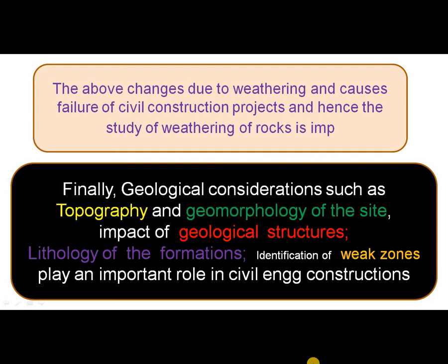And finally, geological considerations such as topography of the area, geomorphology of the site, impact of geological structures such as folds, faults, joints, etc., lithology of the formations in the available site, identification of weak zones in that particular area play a very important role in civil engineering projects.